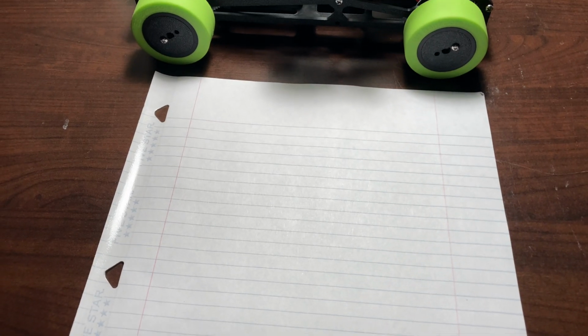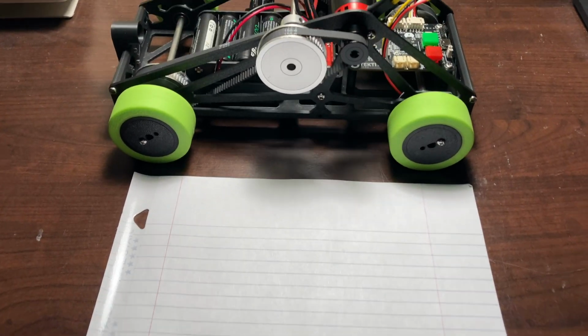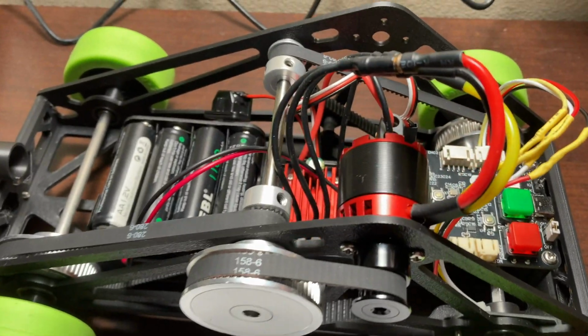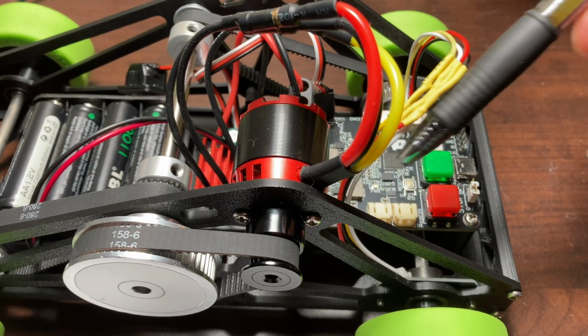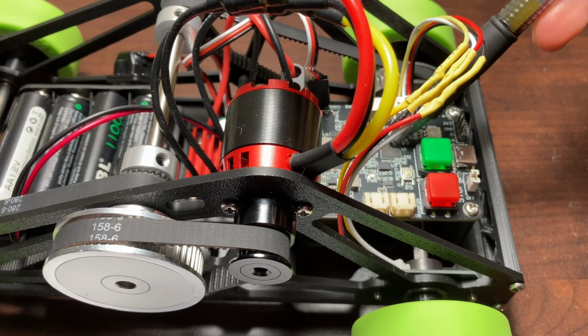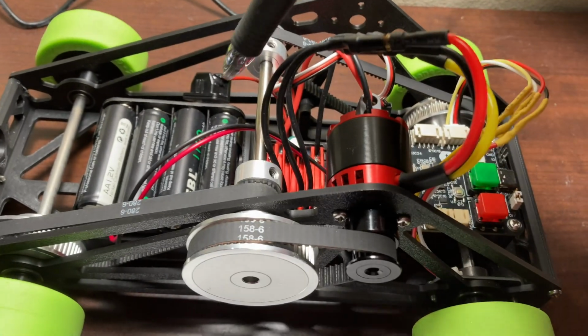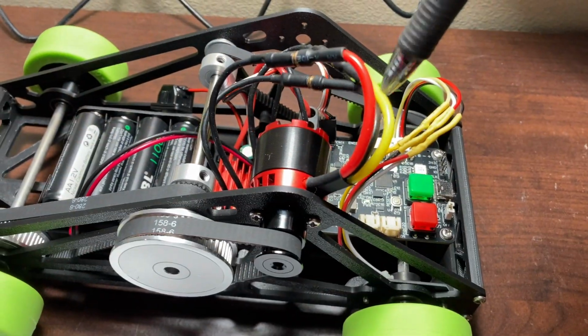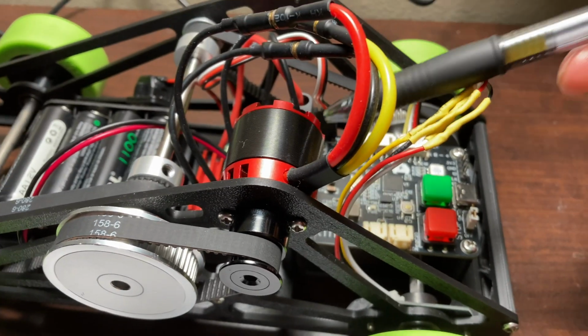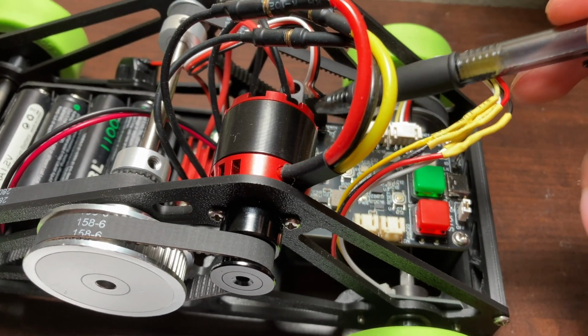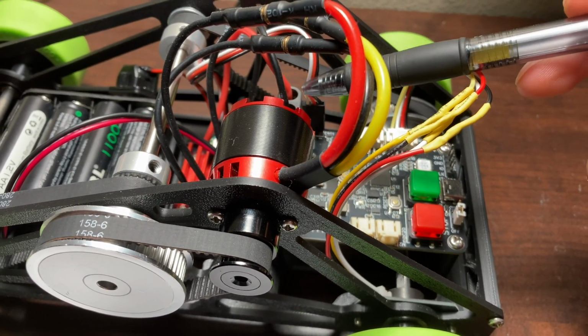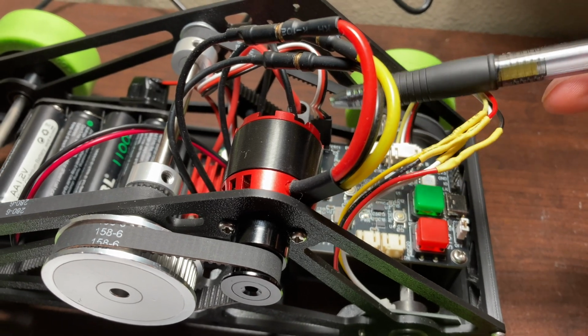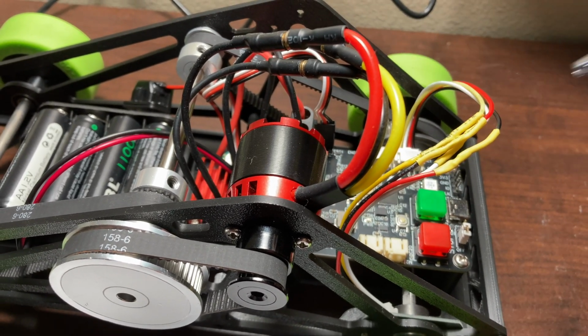Alright, so now let's talk about how you can control the motion of the vehicle. So first of all, note that there's two things in this board. There's the actual CPU over here, which you can control, and there's the ESC, right? And the ESC is what is directly connected to the motor. The way that you communicate with the ESC is over this connector right here. This has a white, red, and black wire. Red and black are power, and white is a signal wire.